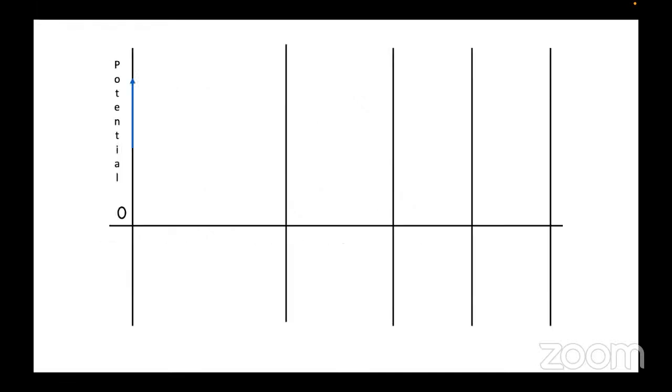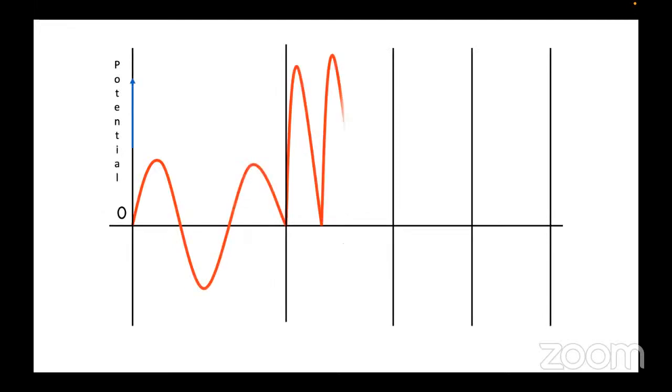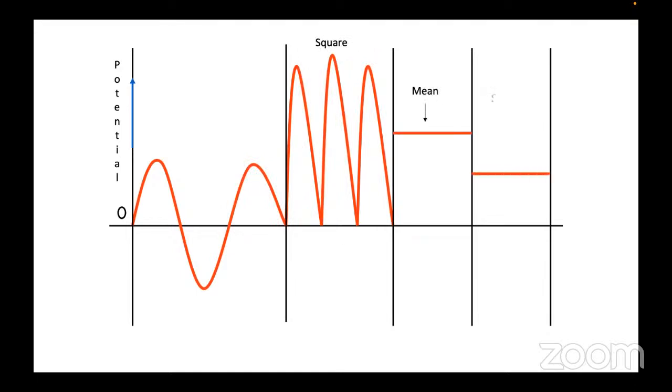So what exactly is root mean square voltage? If you look at the current, which is alternating current, if you square it and then take a mean and then take a square root over that, that becomes root mean square voltage. Okay, so that's how the RMS is derived. And when we talk about 230 volts or 120 volts, that is a root mean square potential.